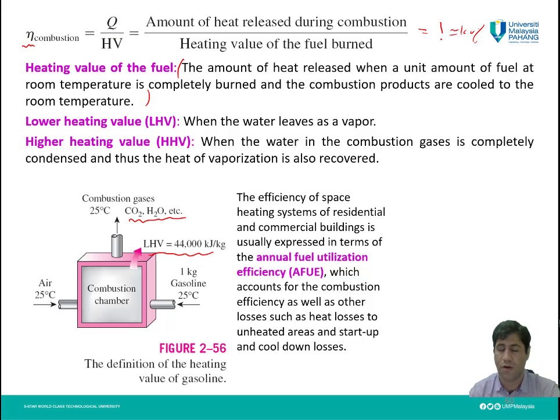If all of the energy is released by this combustion, we call that complete combustion, and its efficiency is 1 or 100%. But usually we don't have that, because we don't have enough reactants like air, and we don't have the temperature required to release all of this heating value of the fuel. We don't have time. Imagine in the engine, combustion takes only some milliseconds. We need time to burn something completely. So the combustion efficiency is usually less than 100%, and very much lower than 100%, I can say.